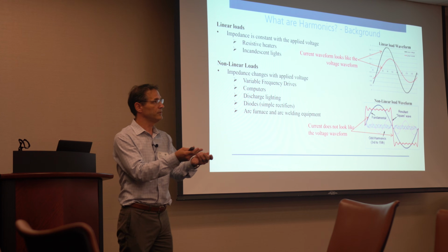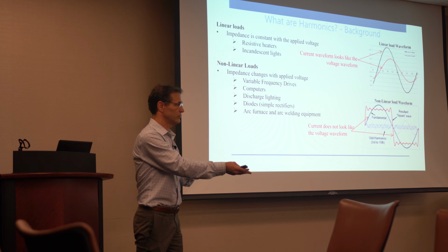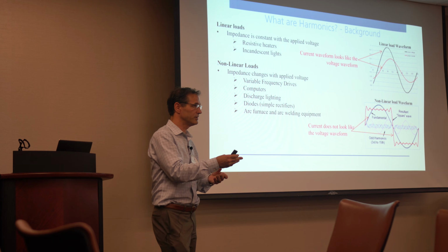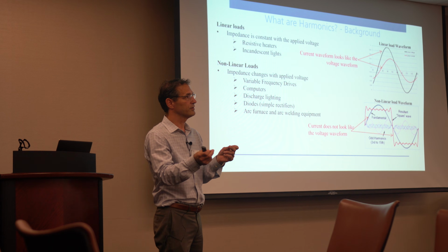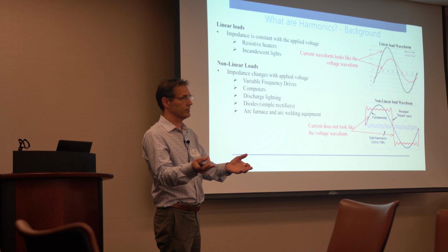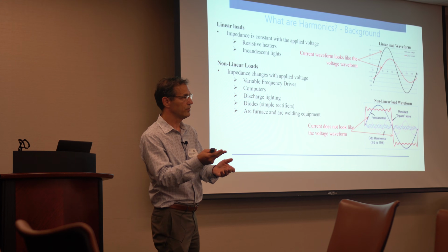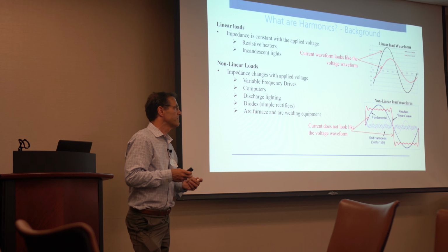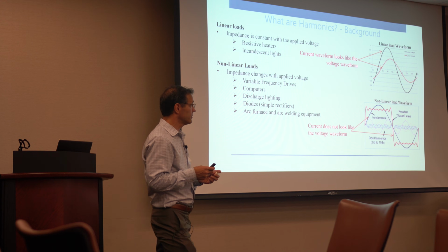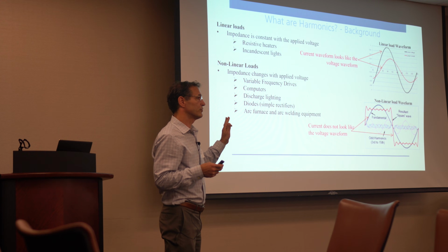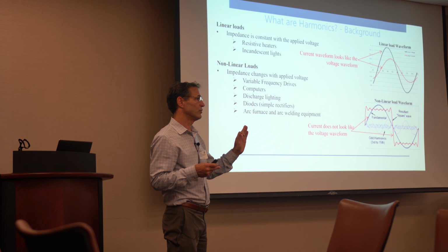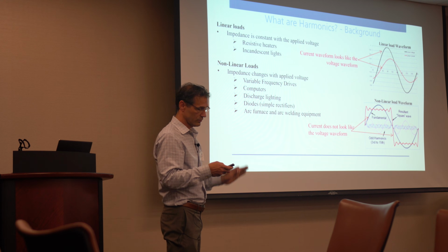If I double the impedance of the source, it's still going to put out 20 amps. Kind of acts like a CT. No matter what burden impedance you put on the secondary, you still get the same current flow for the most part. Which is really the fundamental understanding that those current sources are what is creating voltage in the network.